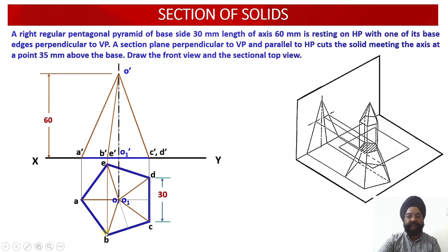So this object line is going to overshadow this hidden line over there. So ultimately this will be drawn dark. Similarly, projections for slant edge O dash D dash have to be dotted because it is lying on the back side, but again they will be overshadowed by the object line, that is dark projections corresponding to the slant edge OC. So that is why this has also been drawn dark or the solid line.